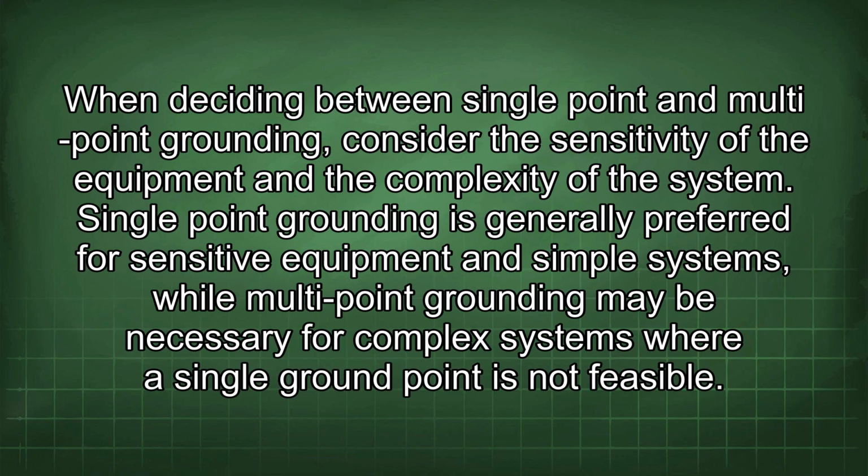When deciding between single-point and multi-point grounding, consider the sensitivity of the equipment and the complexity of the system. Single-point grounding is generally preferred for sensitive equipment and simple systems, while multi-point grounding may be necessary for complex systems where a single ground point is not feasible.